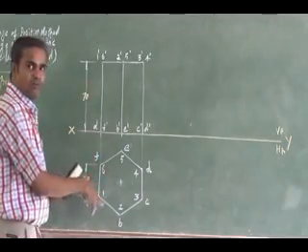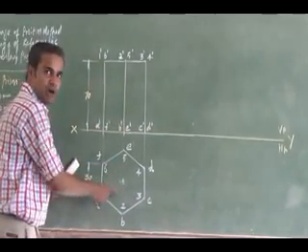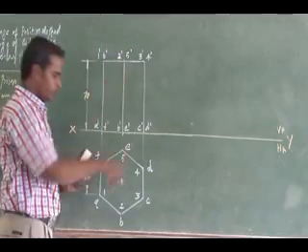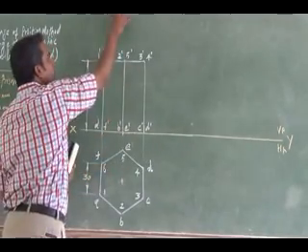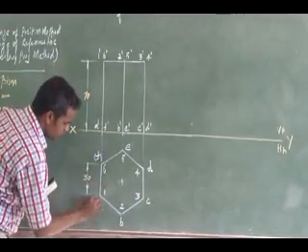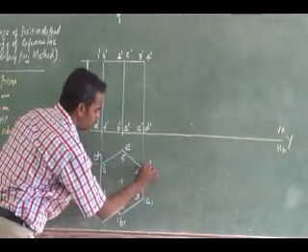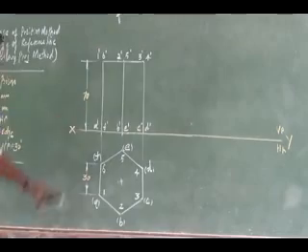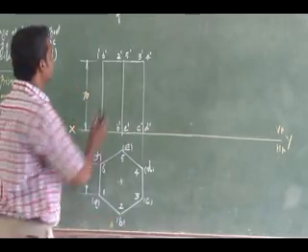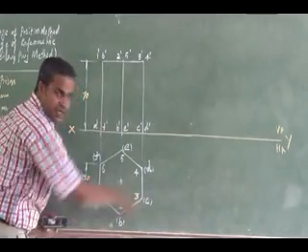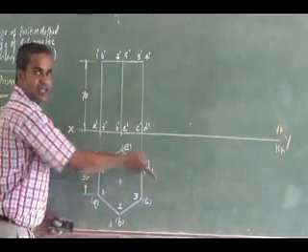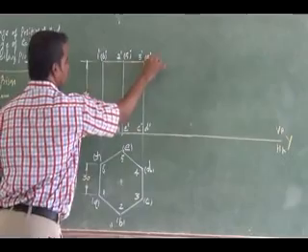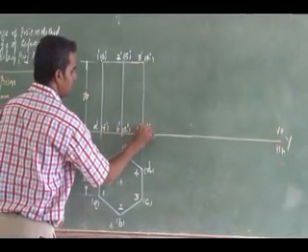Hidden corner. So as for the top view, which base is hidden? You look at the front view from the top. Okay, to mark the hidden details for the top, you look at the front view from the top. ABCD base is hidden. So I have to put it in bracket. Right. Then as for front view concerned, you look at the top view from the bottom, which will be hidden. These three vertical edges will be visible. These three vertical edges will be hidden. That is F, 6, 5, 4, F, E, D.